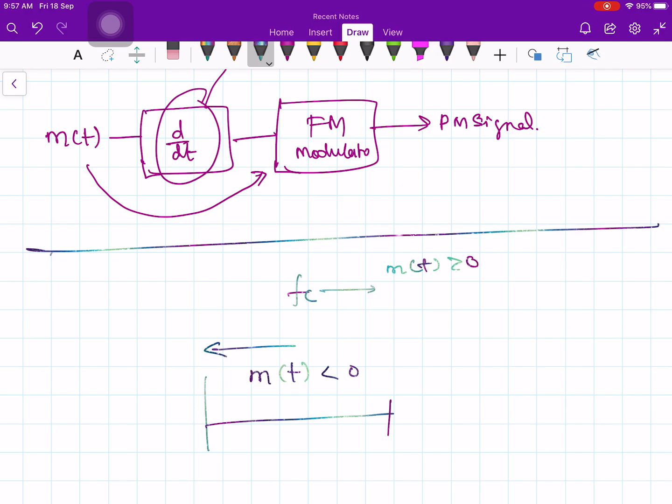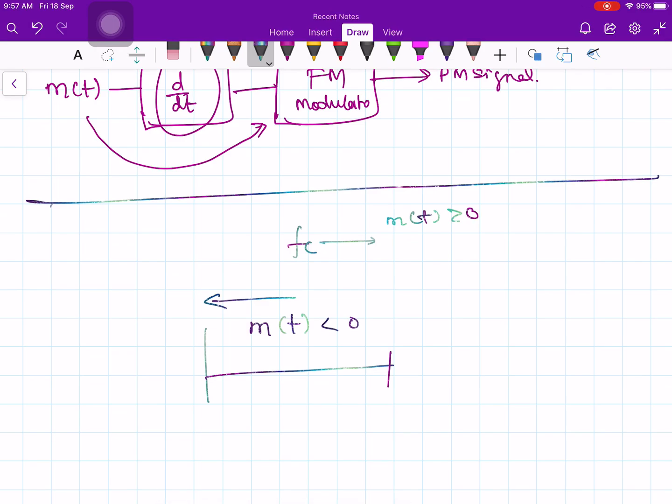Now I need to get an output which is proportional to the input frequency deviation around the carrier frequency fc. There are many ways of doing this. We will consider some of them here. Unfortunately, not all of them will realize the ideal characteristics. Some will and some may not, but they will try to approximate this linear curve. On the frequency axis, it should be a linear curve like this. It crosses the zero point, and at that point the frequency is the carrier frequency, because when the instantaneous frequency is equal to the carrier frequency, the message signal is 0.